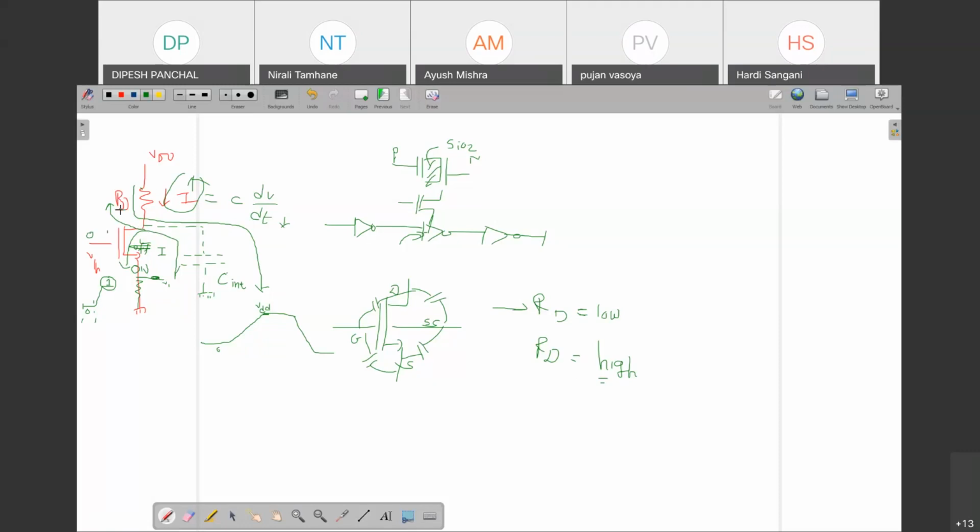In CMOS we use PMOS for pull up. So it will be off while discharging. Any electronic device, any active device, if it is in the on state, it gives a smaller resistance. If any active device is in the off state, it gives a larger resistance. So we use PMOS as a load, NMOS as a driver as it is, with no change in the NMOS, same NMOS. And we apply a common input to both.